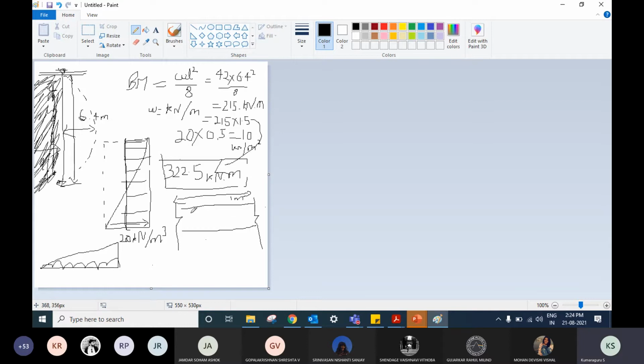Now, this is the face where the rebars are facing tension. So, the tension side of the wall. Like this side is where you have the force, the active soil pressure coming in. So you'll have tension here and compression on this side. Both faces need to be reinforced, but the other side needs just minimal reinforcement.